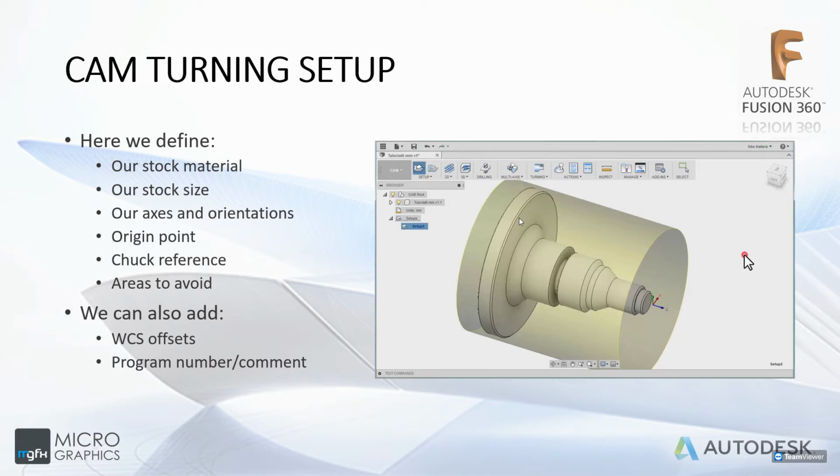You've also got to tell it how much bigger than your model that you've drawn is the stock. Meaning you can see here that the translucent yellow bit sticks out a little bit more than the model, so it's not the exact same size. You've got to mill it down a bit to get to the outermost area of your model, and then start milling inward, inward, inward until you clear most of the material and get the shape that you want.